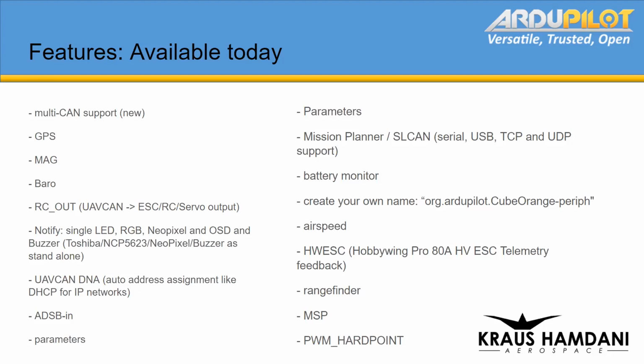And all the nodes work with the UAVCAN DNA. That's the auto assignment for the address or the CAN ID. But things like ADSB and parameters, you can configure all this through parameters, and I'll give an example later of how to do that. Mission Planner has support for talking to this over serial or USB or TCP and UDP.